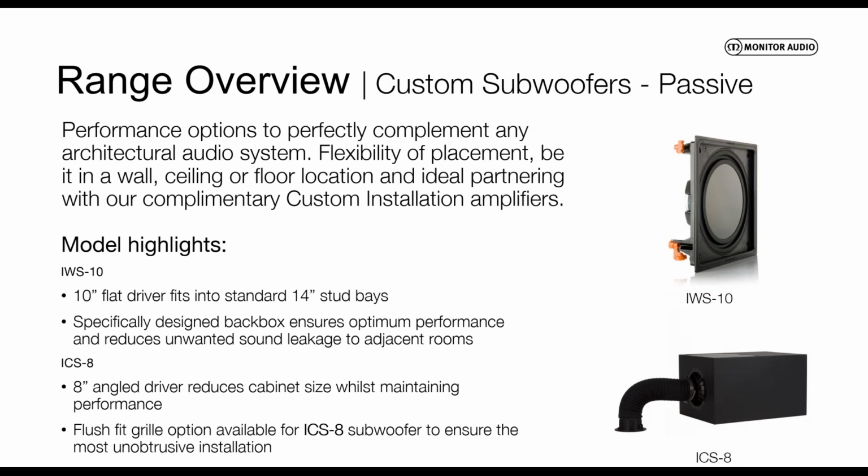Custom subwoofers, we offer 2 passive models. So these are the IWS10, which is an in-wall subwoofer, 10-inch panel using some of our flagship drive unit technology. That fits nicely between 14-inch stud bays, and a single one of those or a pair of those is great for home cinema applications or underpinning stereo in-ceiling speakers. We have a specific design back box. It's not shown here, but that is available to give you the optimum performance, optimum air movement in that back box, and also stopping any leakage of sound. I've already touched on the ICS8, which I won't go back into again, but that is there to underpin our in-ceiling models.